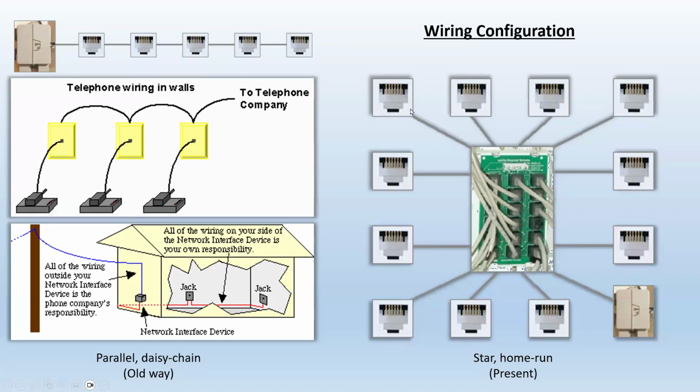If you have a Cat5e connection between one end and the other, and all outlets individually, not daisy chained, then you can use each individual outlet as a data or phone outlet. That's the idea. So any new installations in a residential setting, you would use something like that.